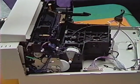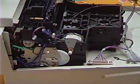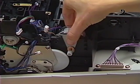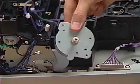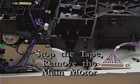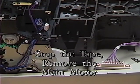Remove the main motor. First, locate the main motor and remove the 2 screws that secure the main motor to the printer chassis. Then lift the main motor straight up to remove it from the printer. Stop the tape and remove the main motor.